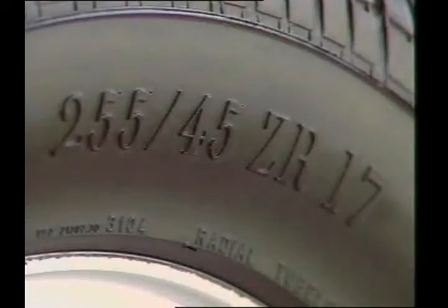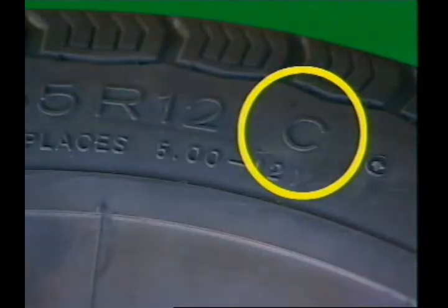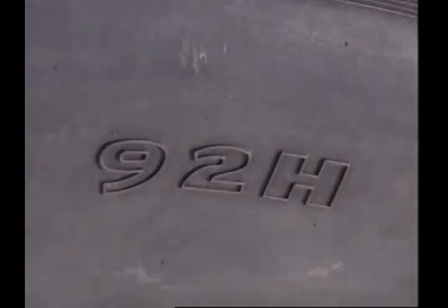Although tire markings may remain traditional, say 255/45 ZR17, there is a worldwide move towards an ISO metric standard which uses letters. P for passenger, LT for light truck, C for commercial, and T means temporary use as a spare wheel. The tyre may have a load index number, indicating the maximum load a tyre can carry at the speed indicated by its speed symbol, which follows the number.